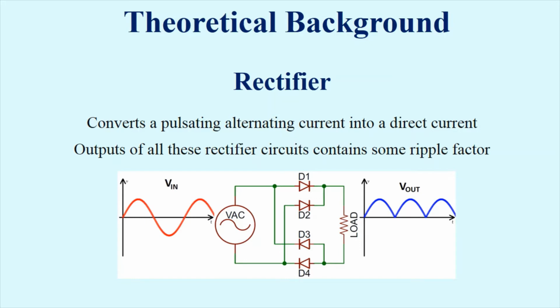Apart from the DC component, the pulsating DC voltage that will be provided by the rectifier has unwanted AC components like the components of its supply frequency along with its harmonics, which are basically known as the ripples. So for most applications, the supply from our rectifier will make the operation of the circuit poor. If the rectifier output is smooth and steady, then overall operation of the circuit becomes better.